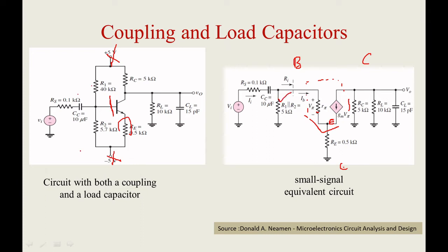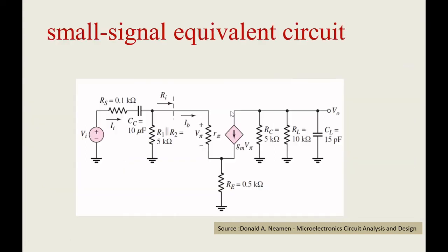I want to find the impact of the input coupling capacitor, so I consider it in the equivalent model. So then RS, then VA. Similarly, on the right side you can see RS will come to the ground. RL is already disconnected from ground, so CL is connected to the ground. Okay, so this is your equivalent model for this circuit. I hope it was clear. Right, now I have increased the size for your better understanding.